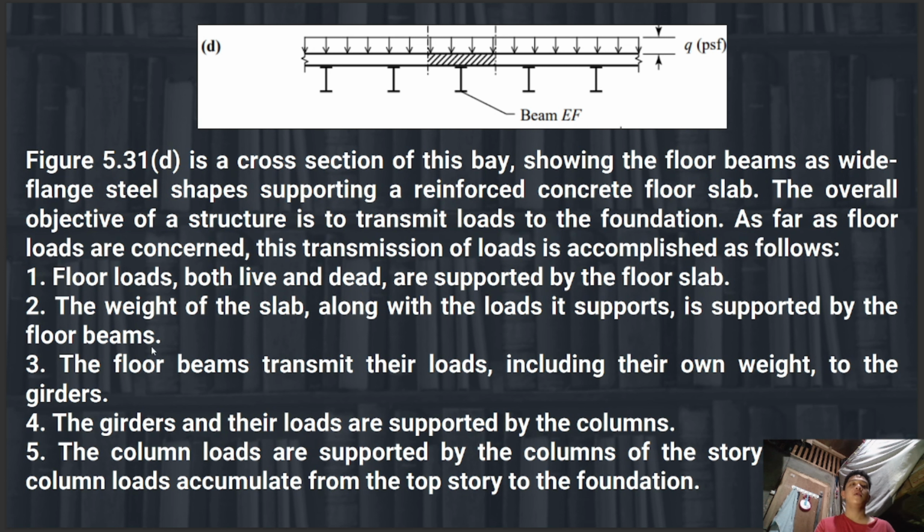As far as floor loads are concerned, this transmission of loads is accomplished as follows. Number one, floor loads. Both live and dead loads are supported by the floor slab. So our floor slab should be able to support both the live load and the dead load. The weight of the slab along with the load it supports is supported by the floor beams. Our floor slab is supported by the floor beams.